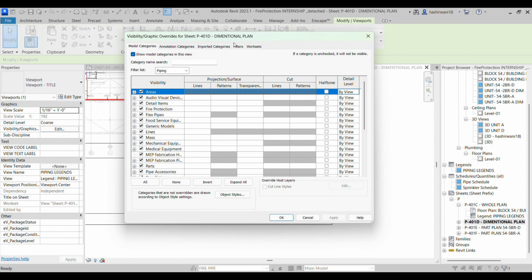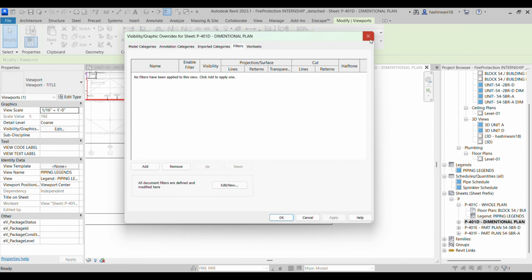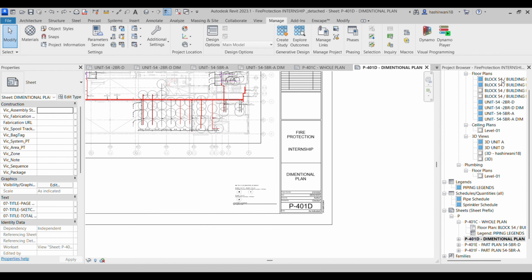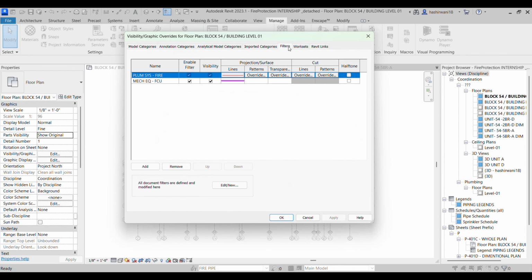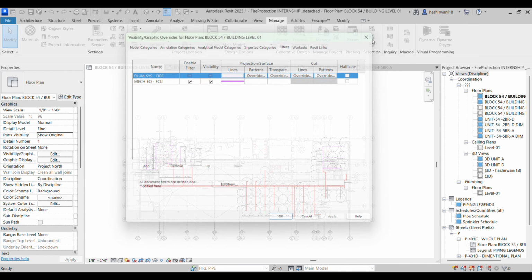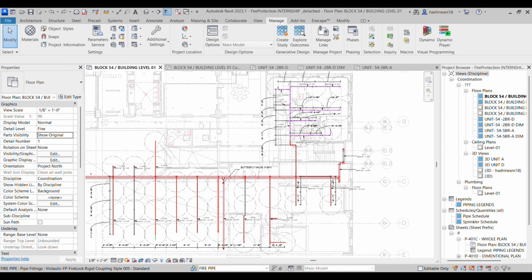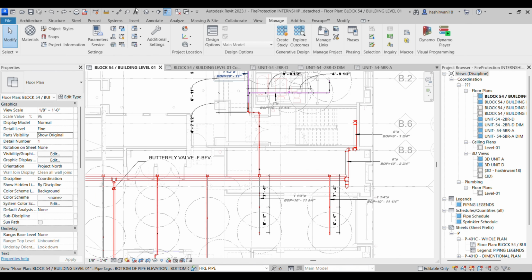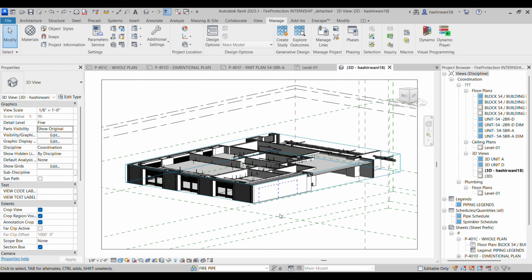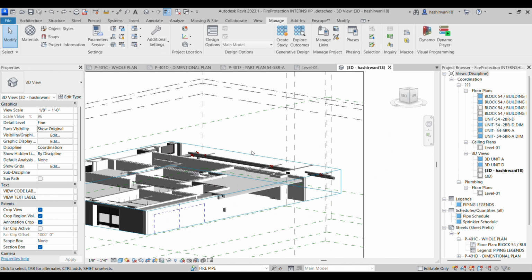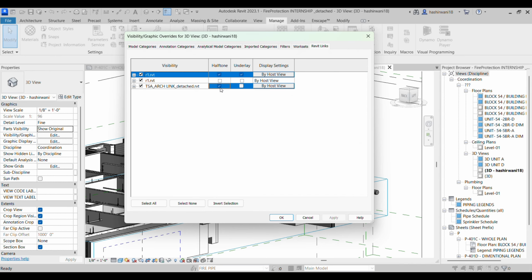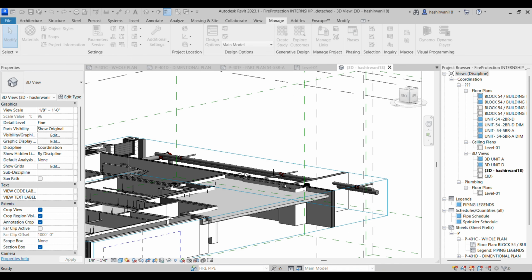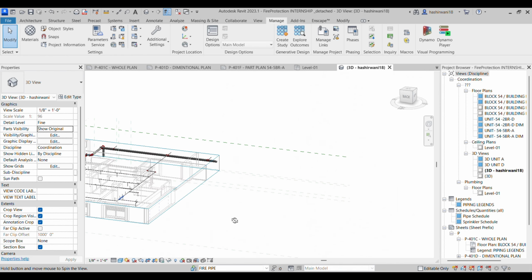If I go to VV, can you see filters? So where are the filters? In this, maybe VV. If I go to VV, do I have some filters? Yeah, I have created two sets of filters here. So in a similar way you can create all the filters. Let me show you guys the 3D of this. So VV, I'll just go to Revit links. I'll just underlay it and I'll just tweak it. So can you see, guys?